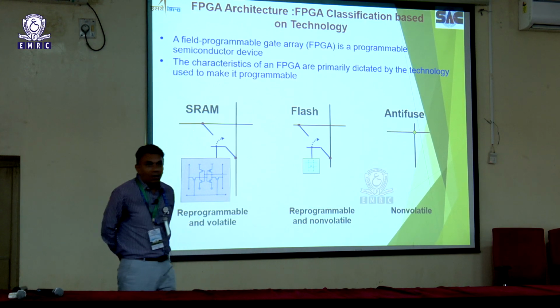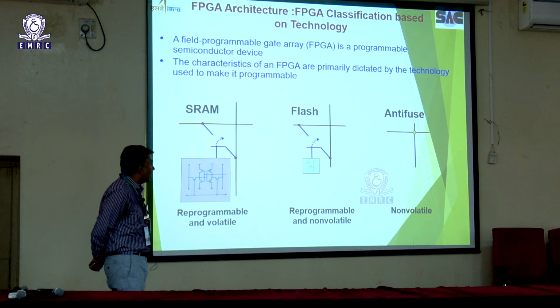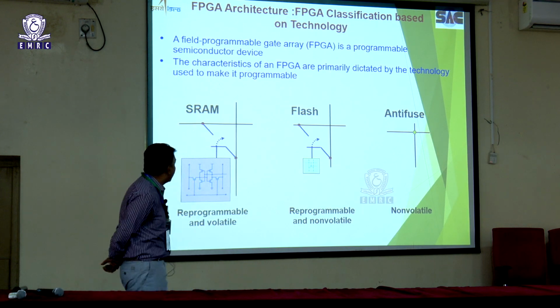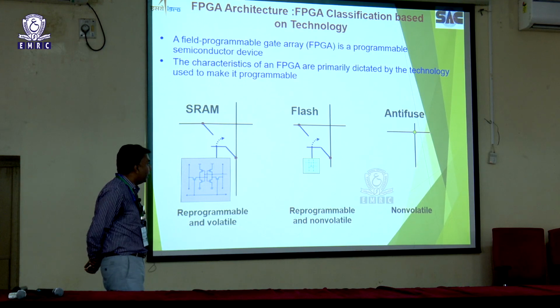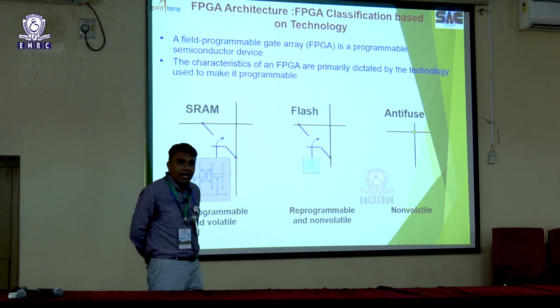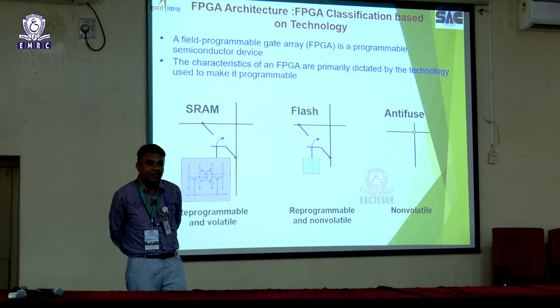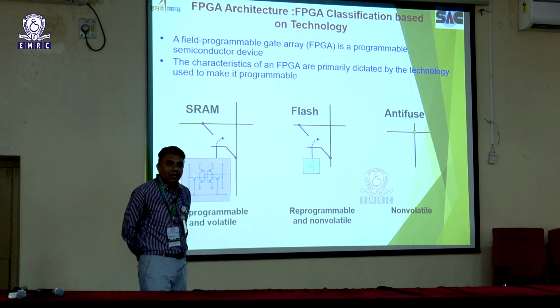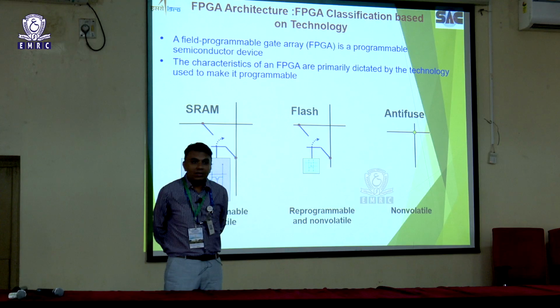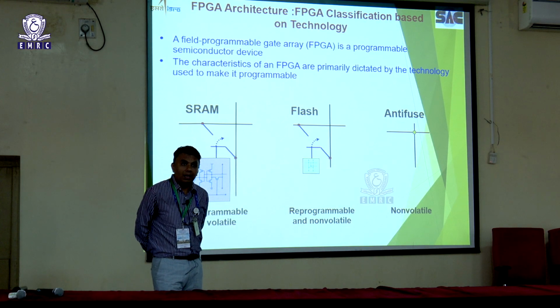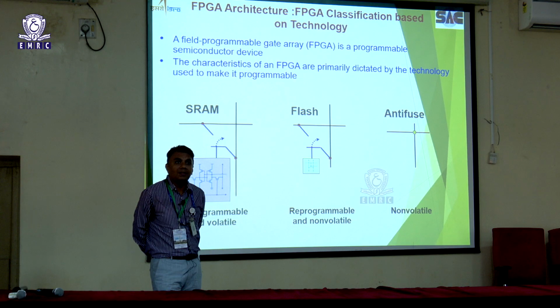Now in terms of technology, there are three major technologies in the FPGA market nowadays: SRAM based, flash based, and anti-fuse based. The most reliable FPGA nowadays is anti-fuse. As the name itself suggests, once you program the FPGA, the logic cannot be changed. So this reliability is enormous, but they have very little flexibility. And suppose by any means some bug is there on the board, you cannot reprogram it.